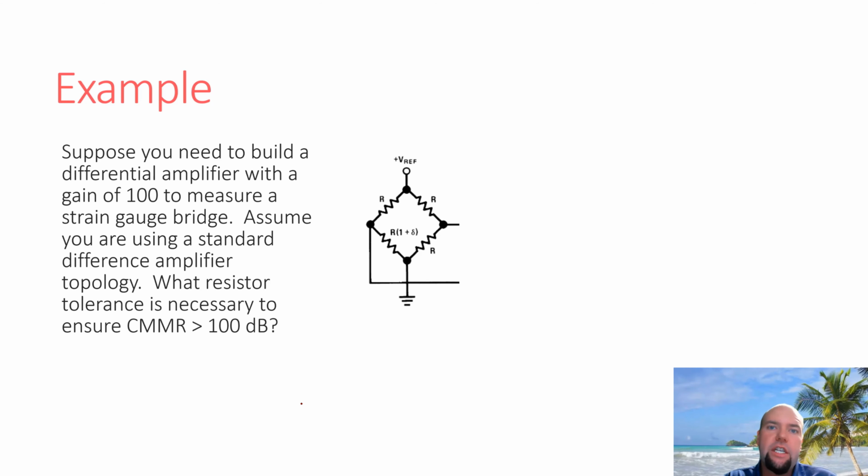Easy enough. The challenge is that if you do it that way, any noise on your voltage supply is going to show up in your signal, which can sometimes be huge. It's very common for voltage supplies to have 1% noise. That would be considered a fairly low noise voltage supply, actually. Usually, a 5-volt supply, like the USB standard, I believe, is 100 millivolts of ripple. So 5 volts, 100 millivolts, that's 1/50th. So 1/50th of your supply signal is noise, which would mean if you're measuring resistance using a voltage like that, you're automatically getting 2% noise.